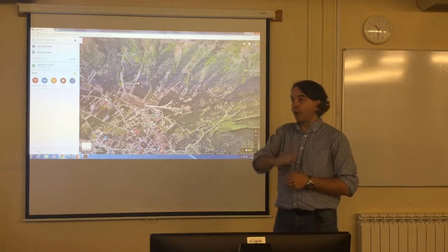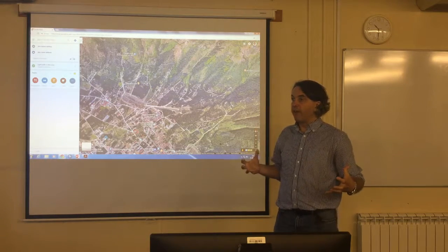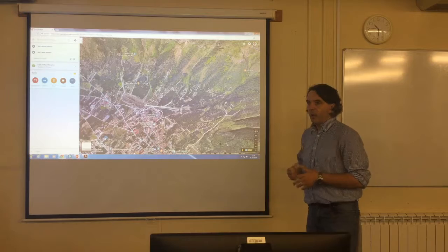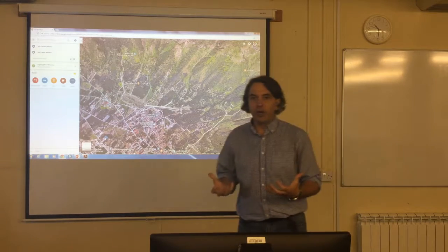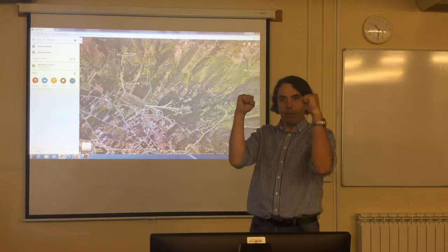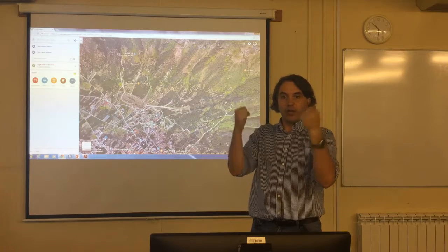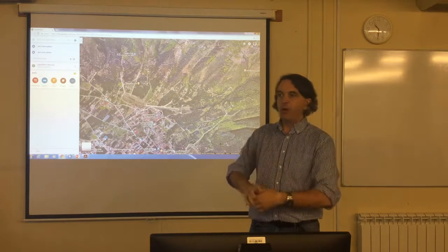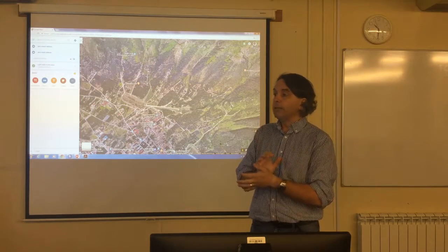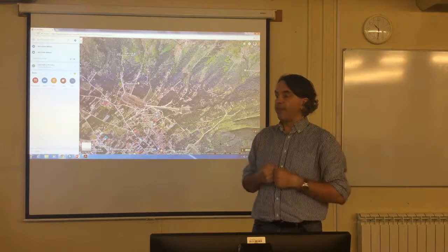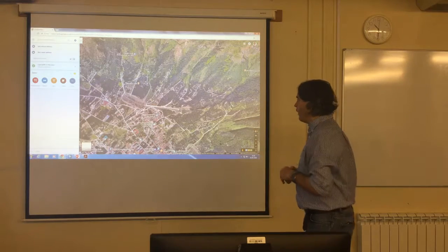So reduce the angle, make the channel really rough, and they've also put in other, what they term sacrificial mitigation, which are things like big metal bars, okay, which are designed to take the impact of the debris flow. They'll be destroyed, probably, but they are there to try to mitigate. So they put in a whole suite of mitigation.